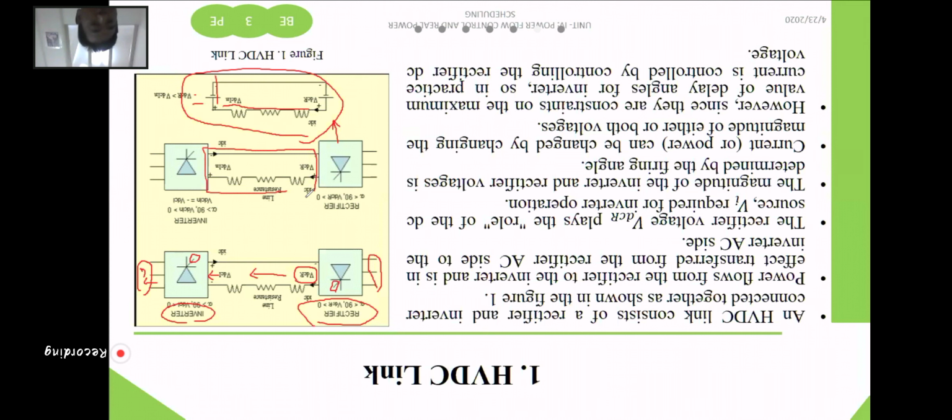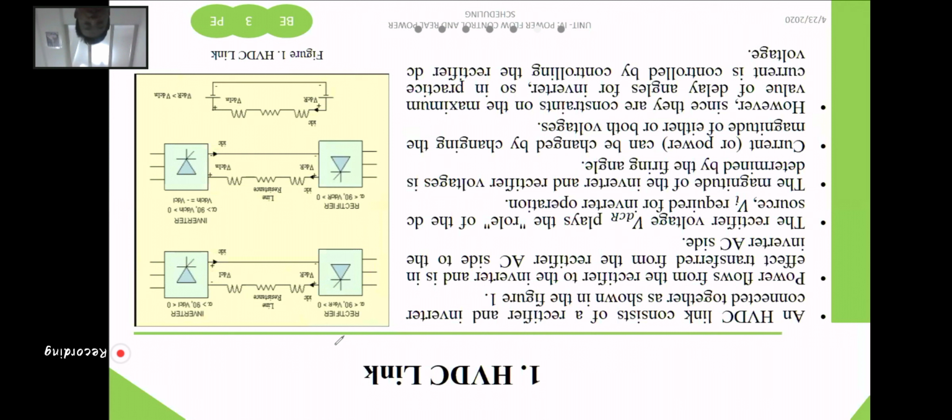In this transmission line system your source is DC because it has been converted from AC to DC, and towards the end, to function the inverter we require a DC only, so we can reflect it by DC, but in the actual case it will convert to AC. This is how we can transfer the power using the HVDC link, or how we can control the power flow using the HVDC link.